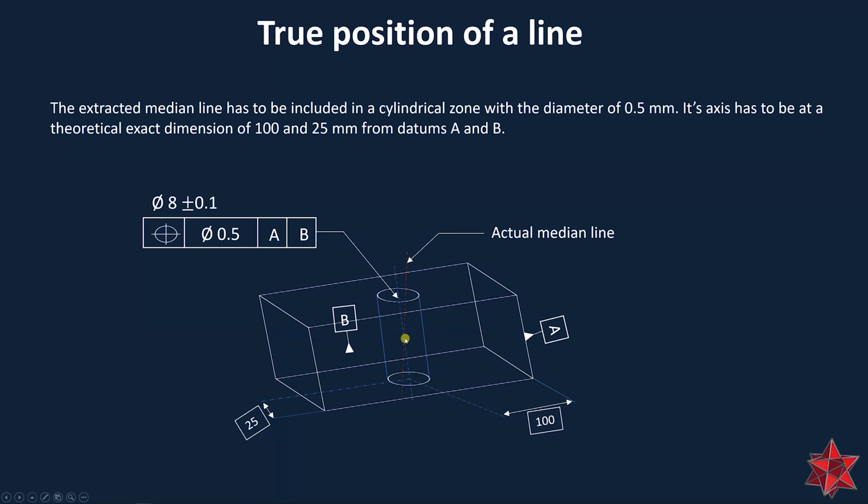Most likely it will be, like in this example, closer to the nominal value, and another section at, let's say the part is 50 millimeters, then we will see at 45 millimeters a section right here, and we have to evaluate the true position, and the value will be in the other direction. So at the top it will be in the plus direction, at the bottom it will be in the minus direction from the center.